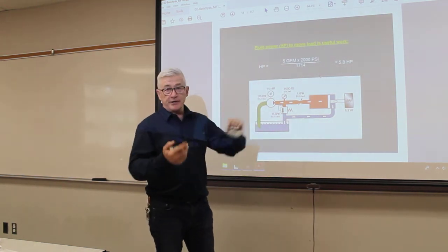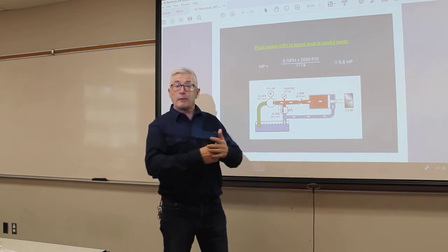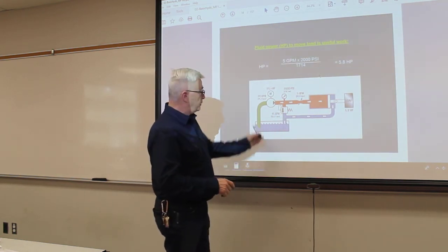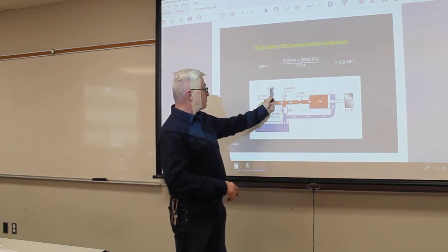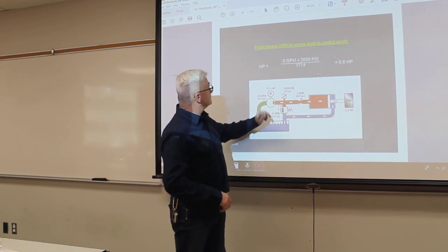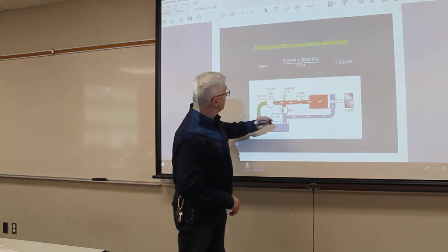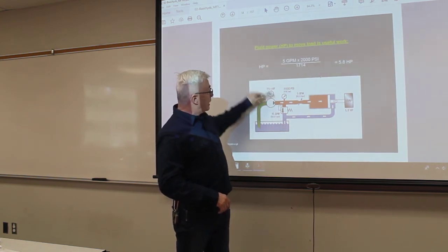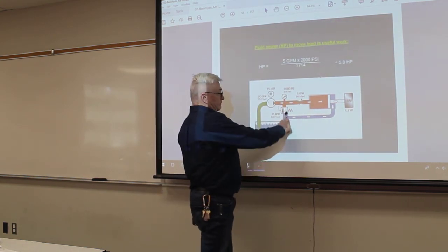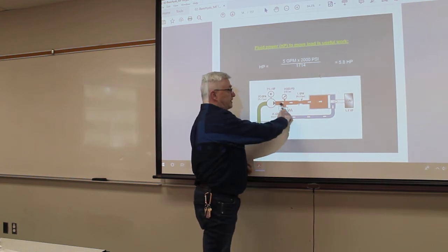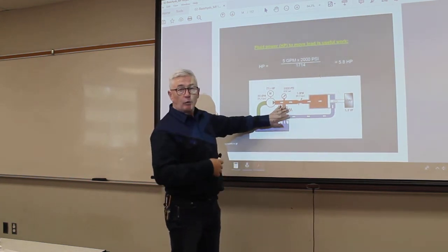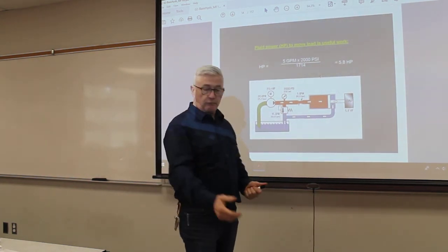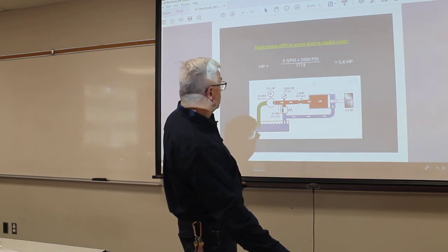We cannot create or destroy energy, but we can transfer it from one form to another. And so in this case, we're putting 23.8 horsepower into here, which means that some of that work is being done to the oil, and it will warm it up. So we're converting one form of energy into another.